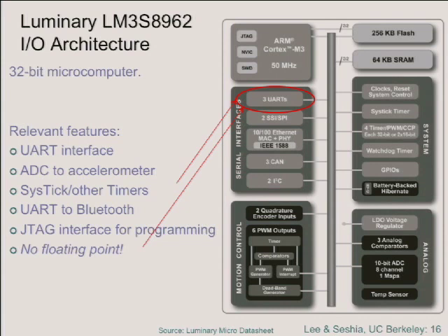It turns out that the performance has gotten to the point where those differences in propagation delay limit the performance of parallel interfaces. And with serial interfaces, you can crank the rates way up and you don't have that synchronization problem. So serial interfaces turn out to be technically better for many reasons, even though it's slightly counterintuitive, because you would think more resources would be technically better than fewer resources. It's not always that way. Any other comments or questions?